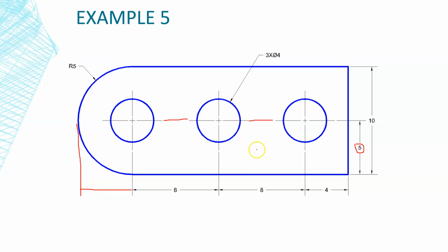You're going to see on some drawings where they may give you this length here, and they may do away with this radius. So if you have this length, you don't actually need this radius. But what I want you to do is look and see how far that is. When you see the word radius, that means it's the distance from this center out to any part on this circle. That's super important. So the distance from this center to that quadrant or midpoint of that arc should be 5. It's really important that you understand this concept, because on some drawings they will give you this radius, sometimes they will not.